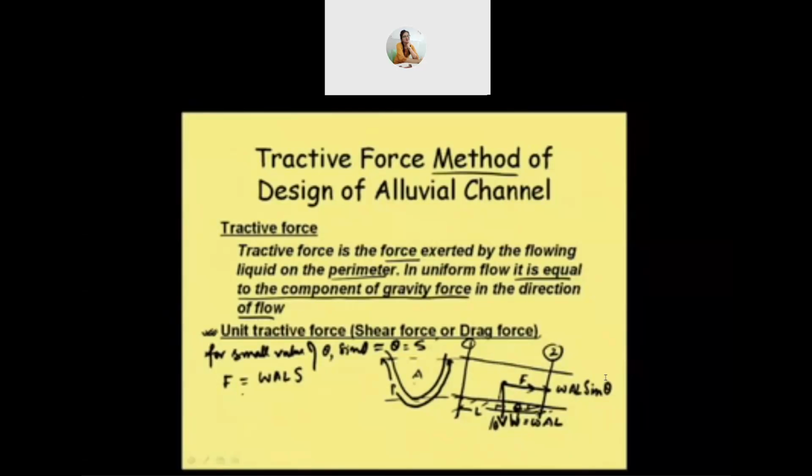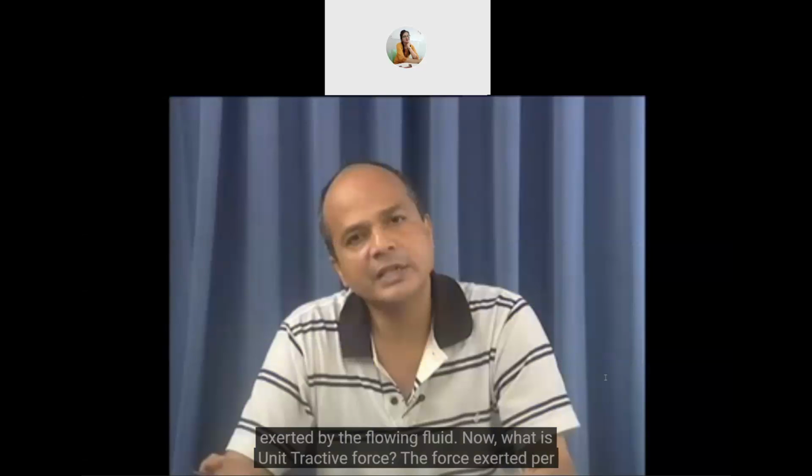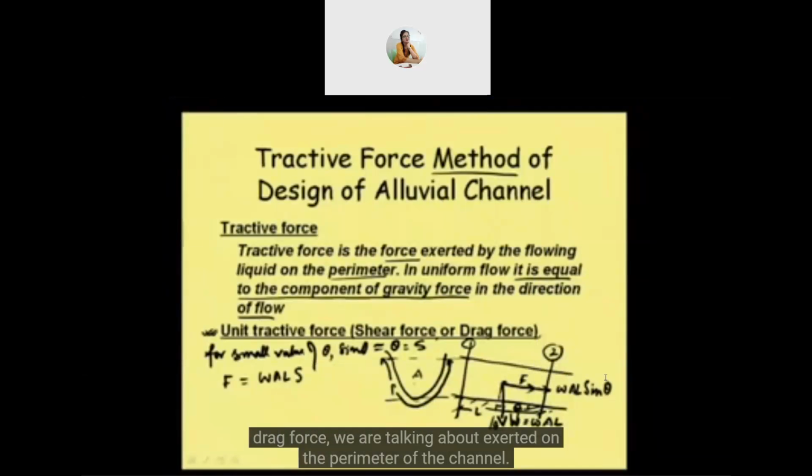Now, this is the tractive force as per definition. The force exerted by the flowing fluid. This is the force which is driving, so this force is taking the water. But now what is unit tractive force? The force exerted per unit area. So what is the total area? Here we are concerned about drag force exerted on the perimeter of the channel. So the total surface area will be this perimeter into the length. If I talk about the channel, it is basically going like that. This length is the same as what I am drawing. So this is the total surface area.